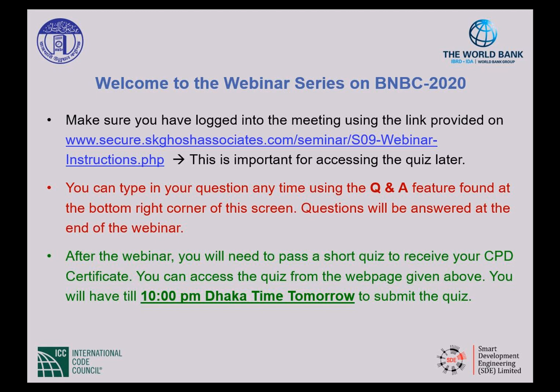I do not know without checking if in Bangladesh you have a value for T sub L. You will get into the third branch only for very tall buildings, 40 stories and higher, or very long span bridges. So most of the time we do not deal with T sub L or the third branch. So I don't even know if you have the third branch in BNBC.